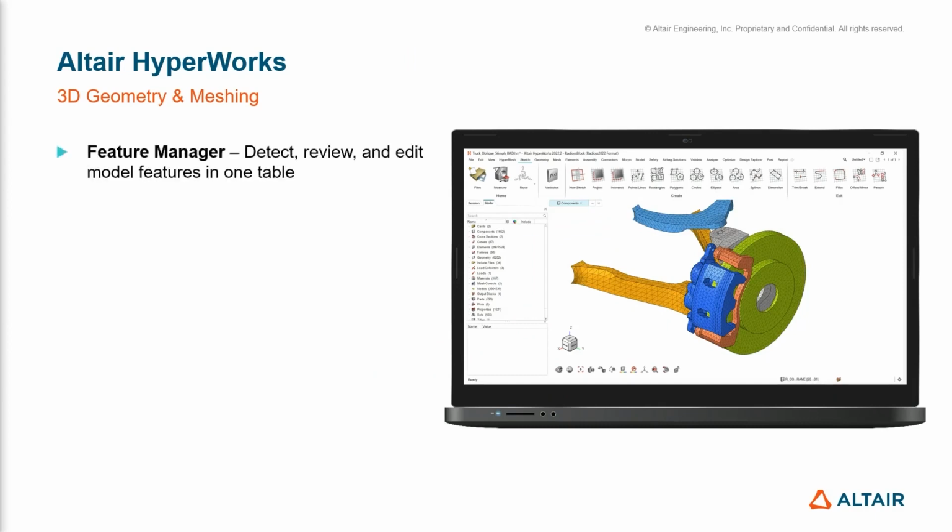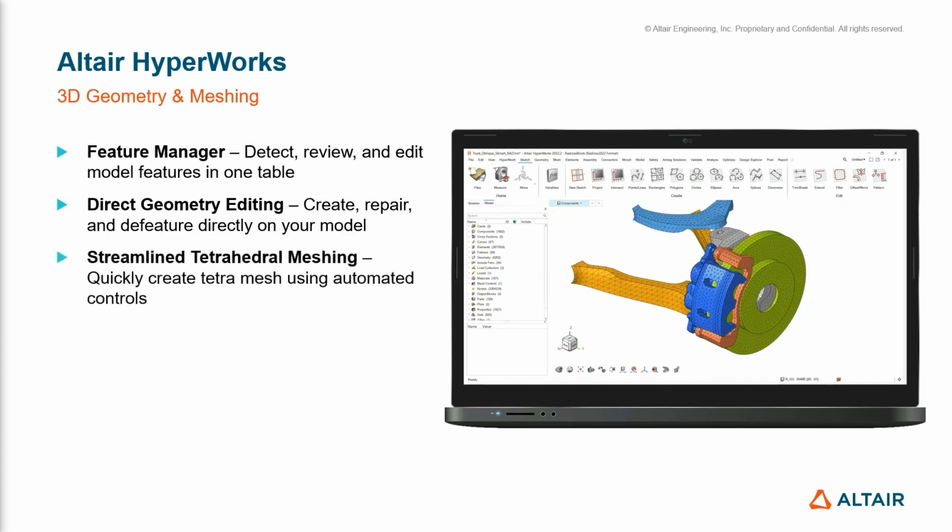First off, we looked at the feature manager and how this allows us to detect, review and edit model features in one simple to use table. Next up, we looked at direct geometry editing and how we can create, repair and defeature directly on our models within the modeling window. We then had a look at the tetrahedral meshing workflows and how we can quickly create tetramesh with optionally using automated controls to speed up the process further.